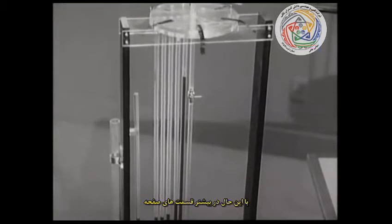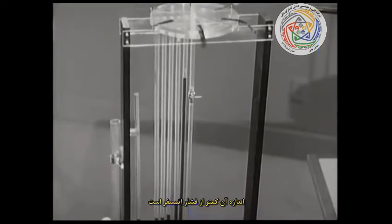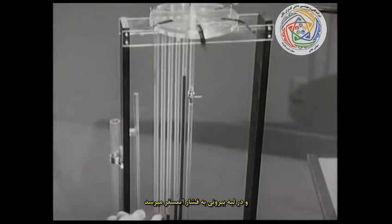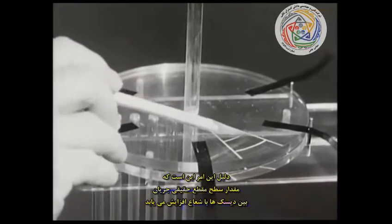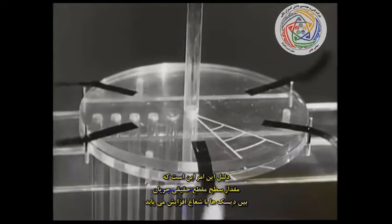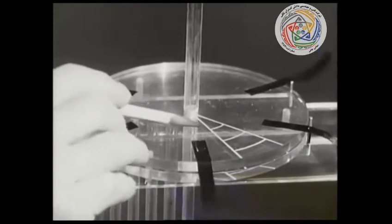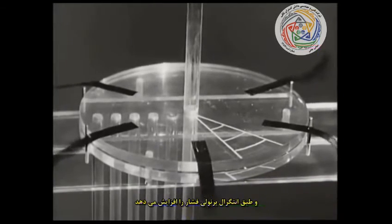Over most of the plate, though, it is less than atmospheric and rises to atmospheric pressure at the outer edge. The reason for this is that the through-flow cross-sectional area between the discs increases with radius. This area increase causes a fluid deceleration, and by Bernoulli's integral, a pressure rise.